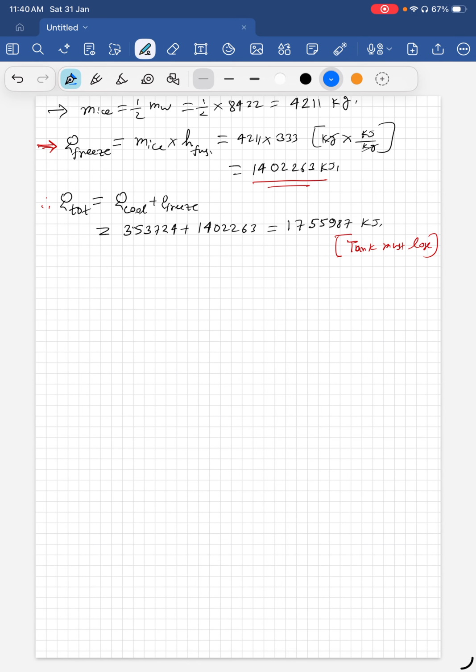So first we are going to calculate the 3.5 hours when the solar system is on. Then the heat interaction will be Q dot of the solar supply, with the heat pump taking out the remaining heat. So 10 minus 3.5, and it would be 6.5 kilowatt.